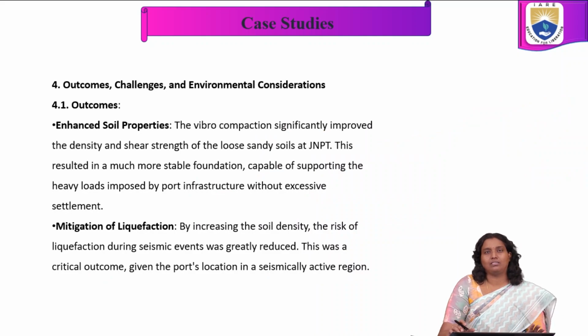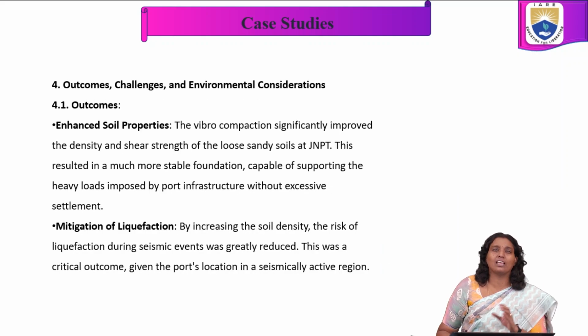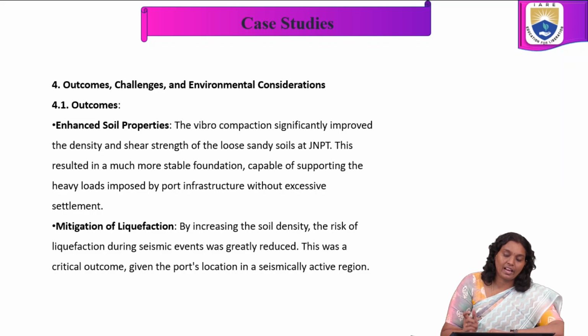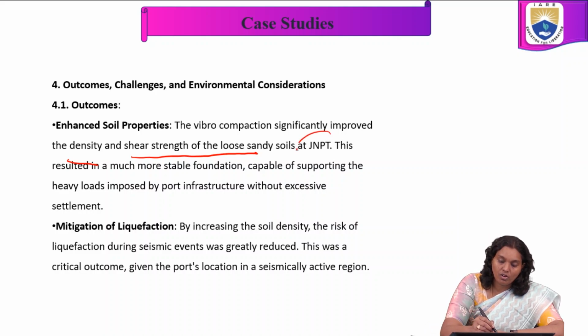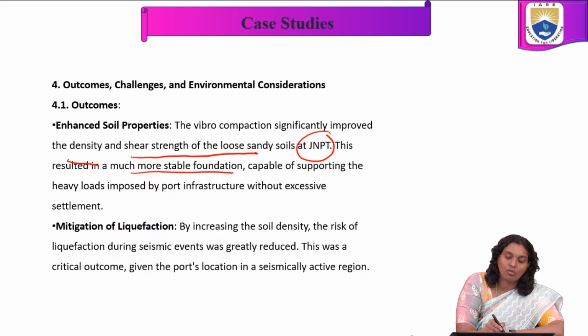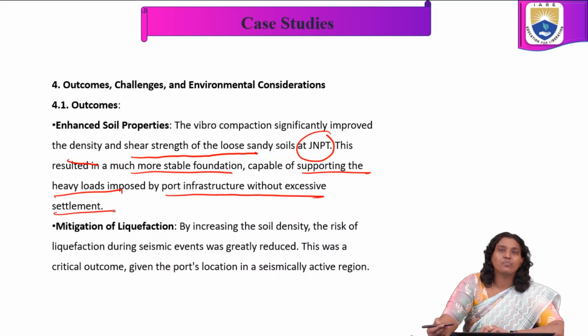Overall, the outcomes are enhanced soil properties and reduced liquefaction risk. As a part of enhanced soil properties, the vibro compaction significantly improved the density and shear strength of the loose sandy soils at Jawaharlal Nehru Port Trust. This resulted in a much more stable foundation, capable of supporting the heavy loads imposed by port infrastructure without excessive settlement.